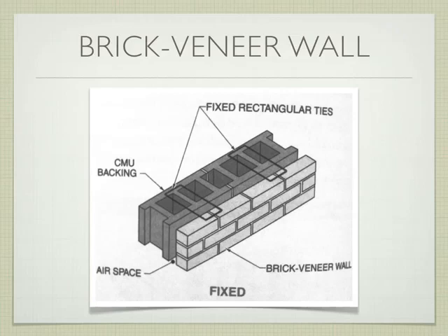But the idea here is that if water gets through a small crack in the mortar, or a small inconsistency in the mortar, or through the brick itself, because it's in a really wet condition, water isn't going to continue through into the structural cavity or into the building itself. There's a gap here that allows any water that comes through to actually drain out to the bottom.